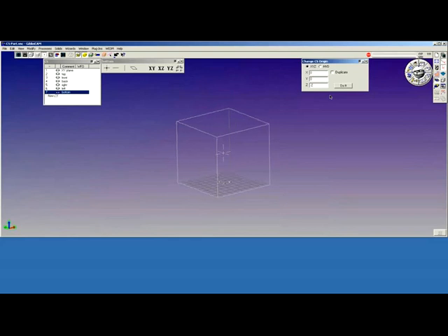The coordinate system moves to the correct location, but once again, my polarity is incorrect. To machine on this CS, I would have to bring my cutter through the part, and that would cause problems. So what I'm going to do is toggle the depth of that coordinate system, and now we see it properly oriented, the negative sign into the cube, the positive sign to the outside of the cube.